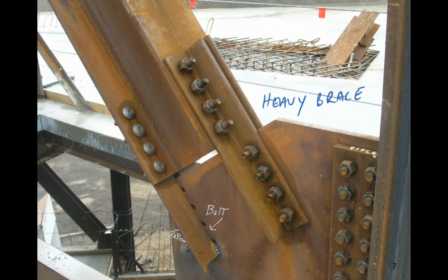And in this case, the flanges are connected to the gusset plate through a combination of the angles on either side that get bolted to the flange and to the gusset plate. In this case, we technically have two tension members. We have the W section, that's the brace, and we also have these angles, right? We've got angles that are basically forming that connection.